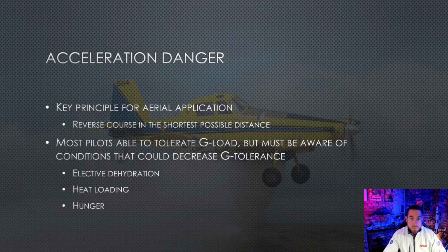There's a risk of acceleration. So you have these repetitive G loads that are being induced. The goal of aerial application is to minimize the amount of terrain you're flying over. So you deliver your spray load, you want to get turned back around as quickly as possible, come back in, deliver your next line, which means that to do that, you're having to pull these really tight G maneuvers to get back on line again. And if you're doing this over and over and over, then that impairs your ability to withstand these G forces for a constant period of time.